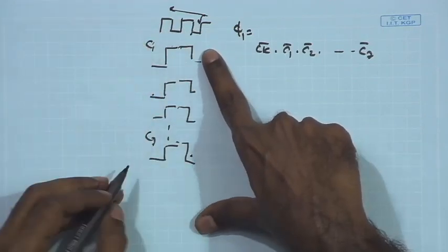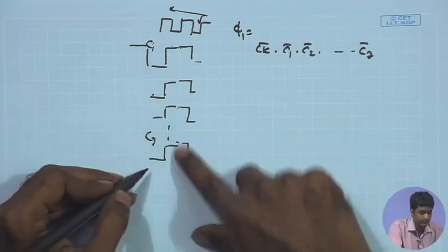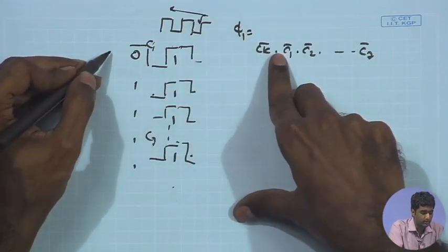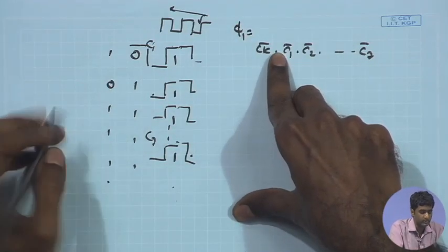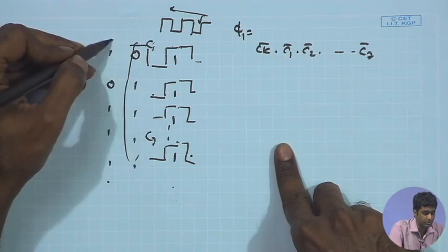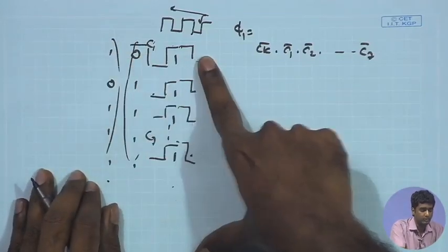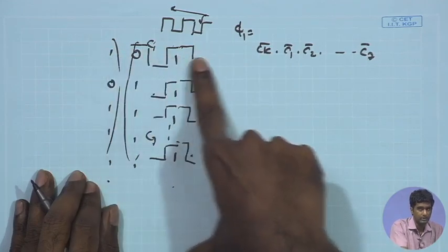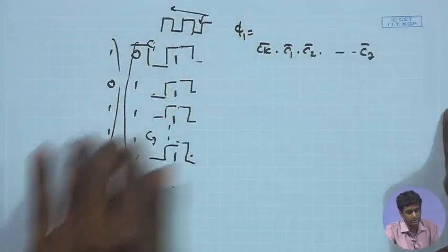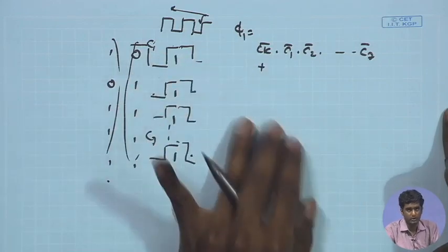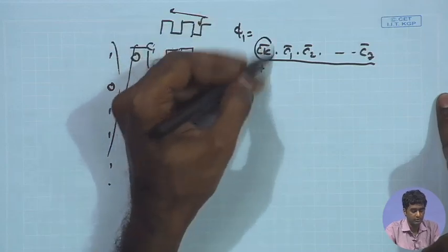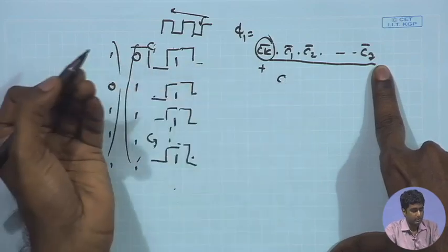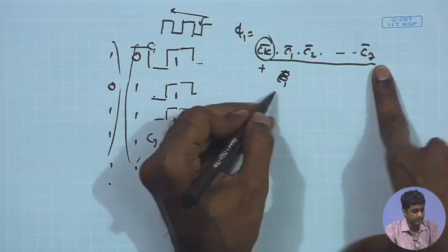That is what we discussed, and for that the only thing you need to do is apply more logic for more counts. Here I am talking about the count of all ones. Before that you will have 0 1 1 1 1, before that you may have 1 0 1 1 1 1 and so on. So, I will apply the logic corresponding to this combination, and whenever these particular phases come for the counter, I would like to keep the phi 1 high for this entire duration. I can just use that additional logic. So, basically it will have another OR gate. If you get the first combination, I may not even use CK in that case. I will just use the counts C1, C2, C7 bar.